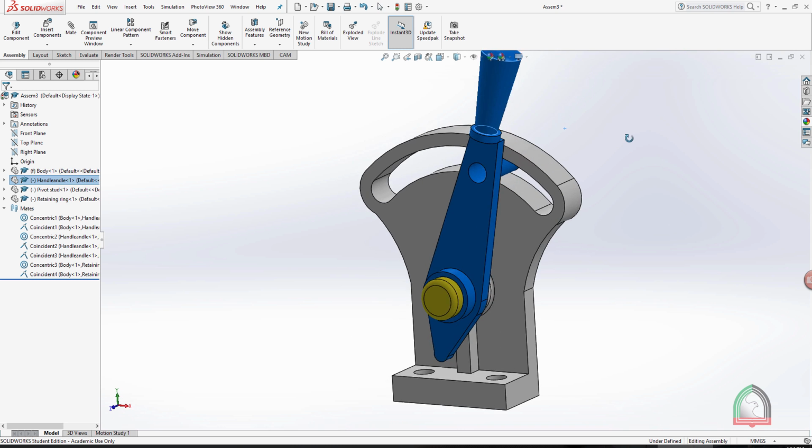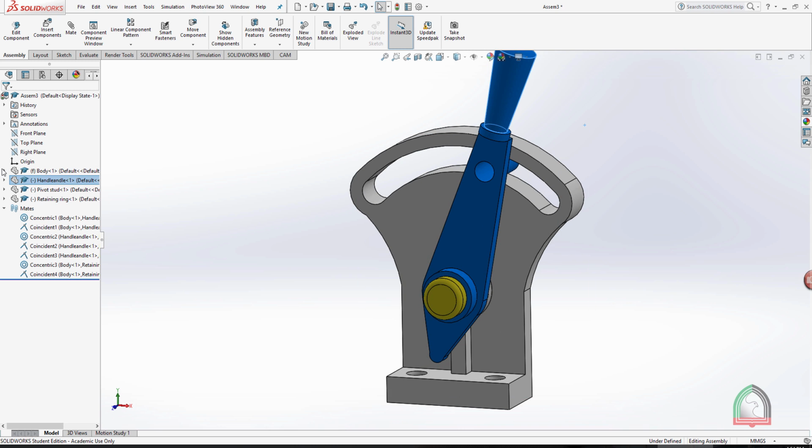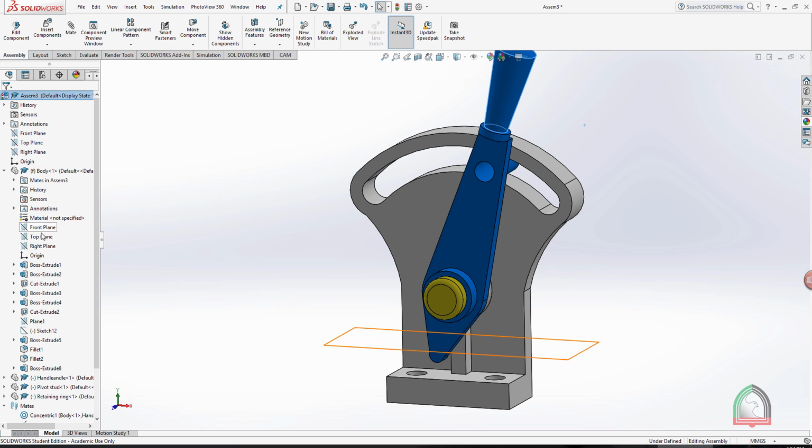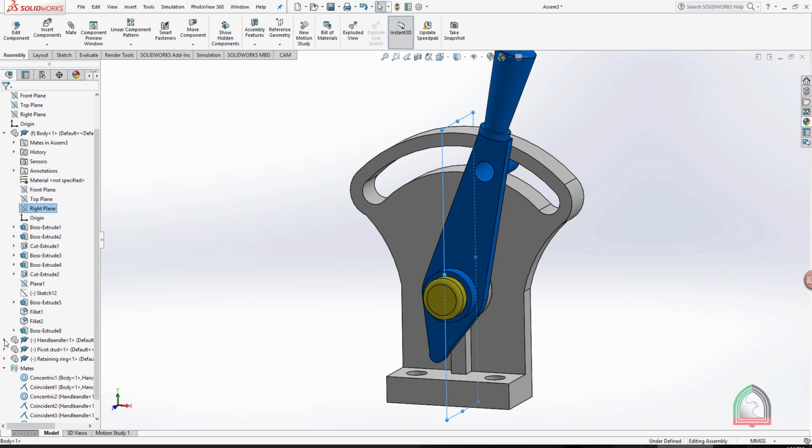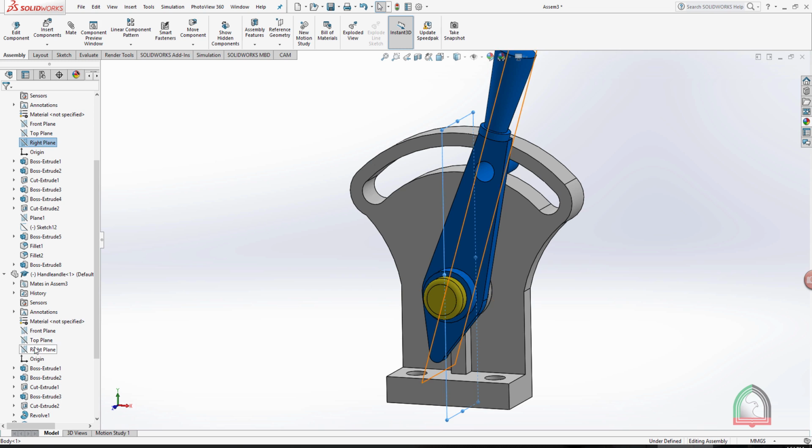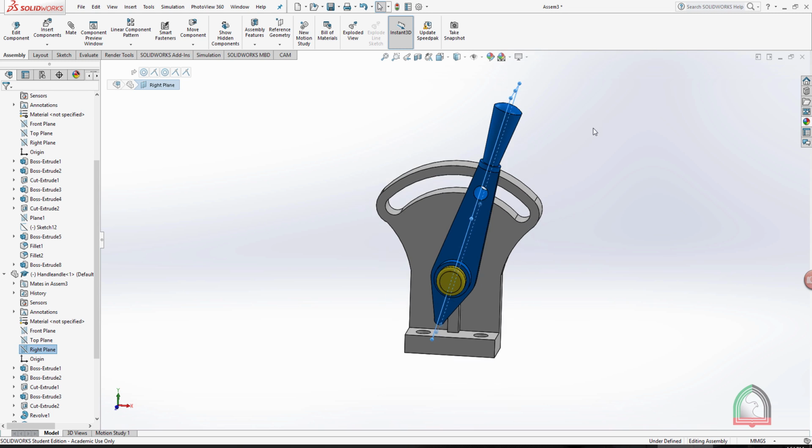And when I am checking the references, we can see that in the body the planes are the references, so no plane is actually making a coincident relation with the center of the circle. And in the handle, okay, the right plane is exactly in the middle. So if we can create a plane by connecting the center and this particular circle, we can give the relations.